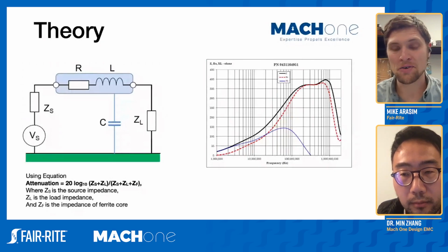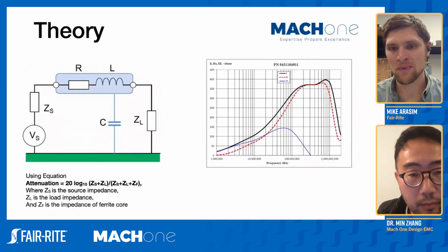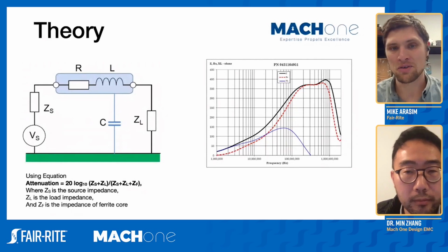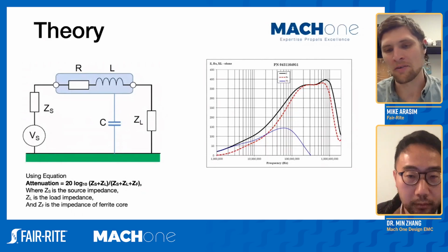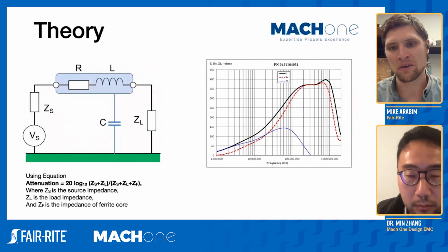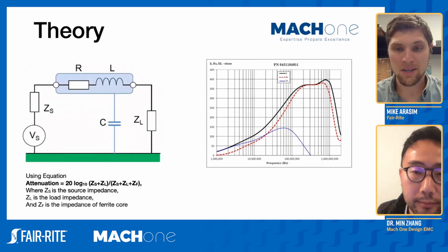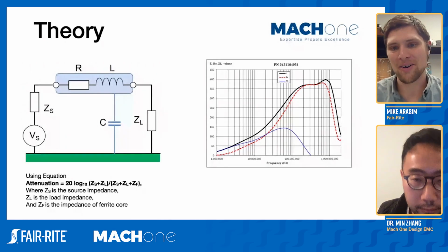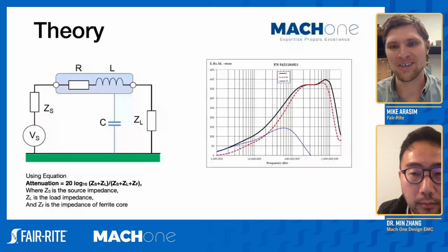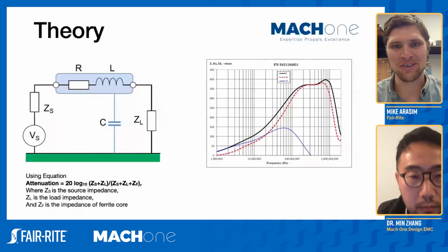From the manufacturer's standpoint, we deliberately try to measure the cores in isolation, just to characterize strictly the impedance of the core. Of course, that's never a perfect thing, because that snap-it core needs a wire. We don't have test fixturing sophisticated enough to eliminate the need for conductors just yet.